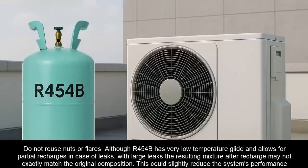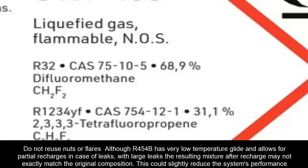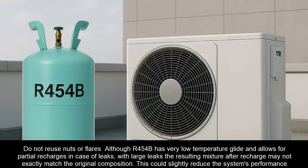Although R454B has very low temperature glide and allows for partial recharges in case of leaks, with large leaks the resulting mixture after recharge may not exactly match the original composition. This could slightly reduce the system's performance.